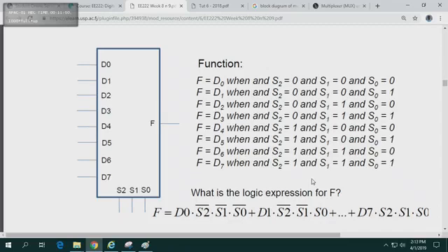You can build a 4-to-1, I call it 4-1, multiplexer using question mark 2-1 multiplexer. Or you can build an 8-1 multiplexer using question mark, or blank space, right, fill in the blanks, 2-1 multiplexer. So what I'm trying to say over here, you can build bigger multiplexers using small multiplexers.